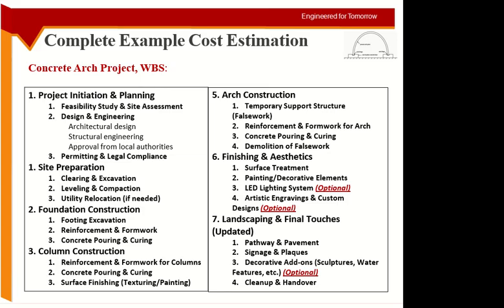Then you have foundation construction. I believe most of you did very well in selecting these activities for the dependencies in the project. So this is very straightforward. You have the foundation excavation, then you have the reinforcement and formwork and the concrete pouring, and after pouring you need to do the curing. Then you have the column, same activities, reinforcement, pouring, curing, and then you have the surface finishing as well. So this is extra here; for the foundation you don't need any surface finishes.